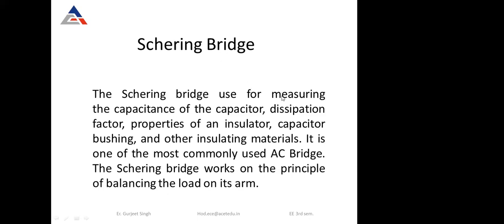Today we will discuss the Schering bridge. The Schering bridge is used to measure the value of a capacitor. This is an AC bridge, and it is used to measure the capacitance of the capacitor, the dissipation factor, and the properties of the insulator, capacitor, bushing, and other insulating materials. Again, we use this bridge to find out the capacitance, or we can also say the capacitive reactance, of the capacitor.